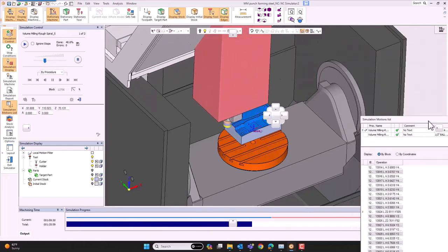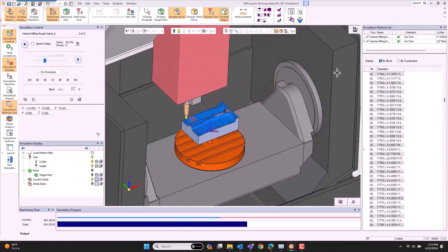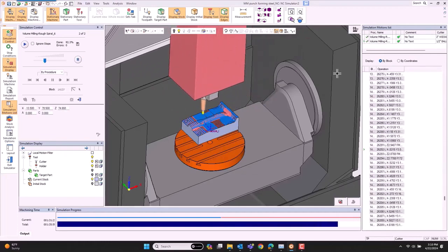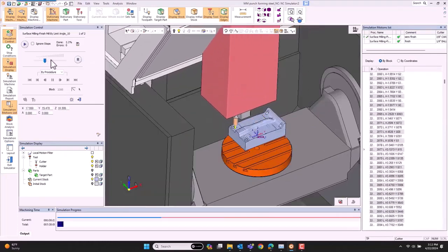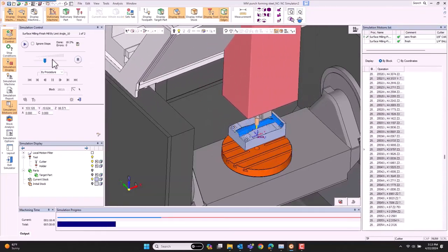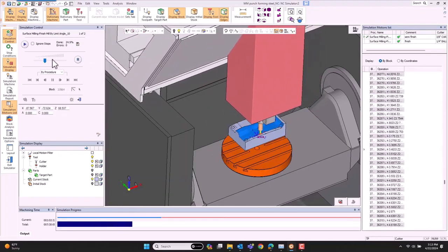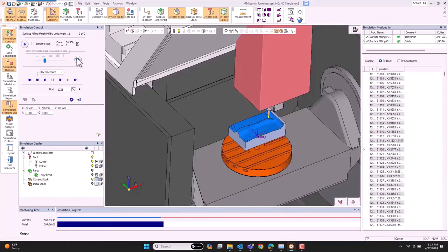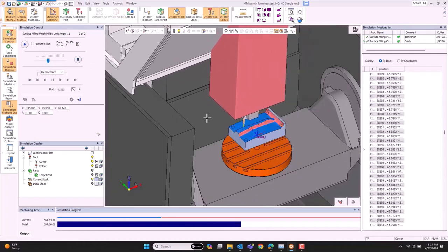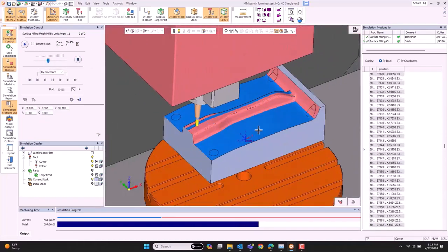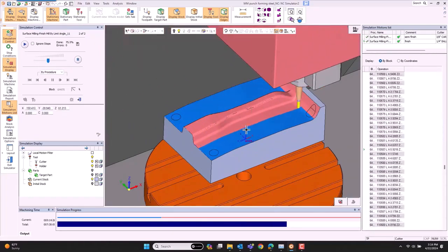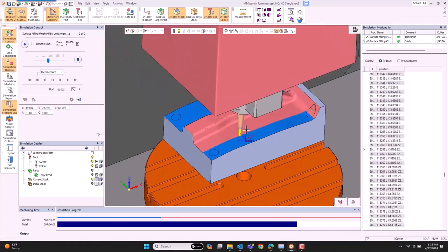All of this, of course, can be simulated. Here you're seeing a full machine simulation. It could be just the individual part, like you see a lot of different simulations plot. Let's pull the G code up, and as I go through the rough cut and now through the semi-finish, you can see how it's targeting just those stair steps, just that remaining material condition. Here you see it taking a Z level and then a lace cut for a finish. So all that is controlled so that I get the quality of cut I want. It could be a remachine too, where I go back and pick out those corners.